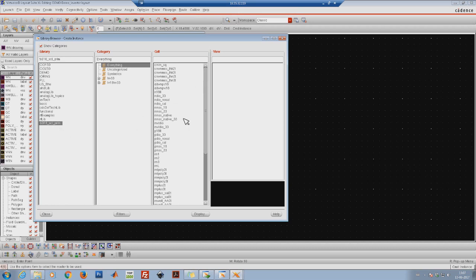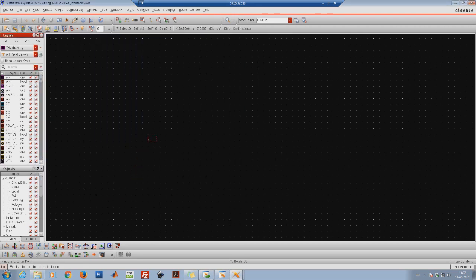So let me search my PMOS first, NMOS. So this NMOS_18. I need to create the layout version of this device. Initially, while I was drawing the schematic, I was selecting the symbol version. So close this library manager, hide it, and you see something is attached to my mouse pointer. Just click the mouse, but still the device is attached. So just press Escape to undo this command.